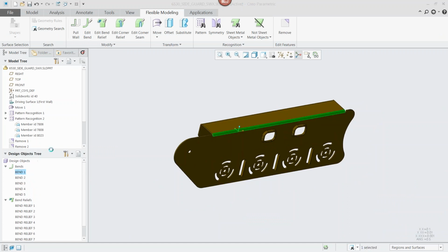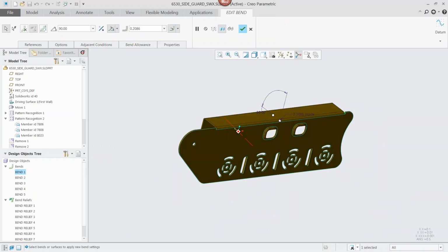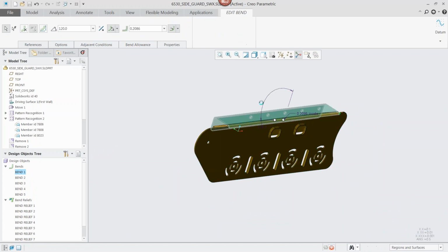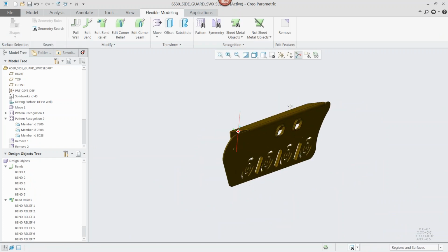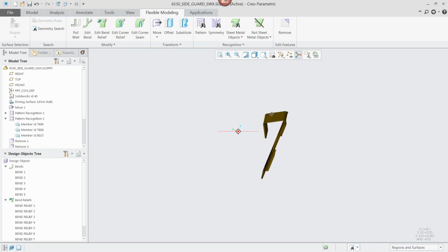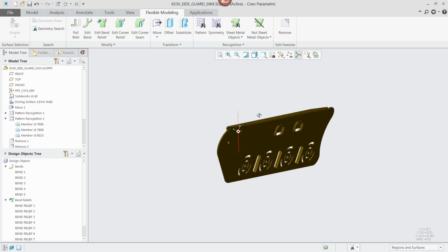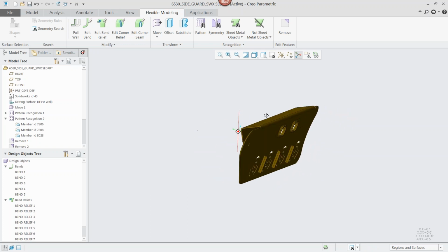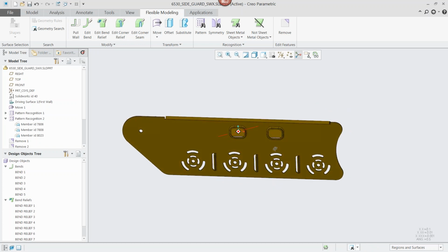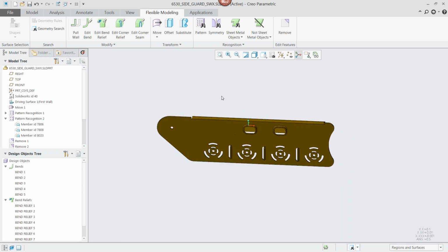Lastly, those bends, if I go through, modify that, maybe instead of a 90-degree bend, we want 120. You can just accept that off, and it's going to change this model. So a lot of different power with Creo on how we can not only bring in imports without having to worry about import failures, being able to natively open, we can also go through and modify those with flexible modeling. So giving us a lot of different things we can do with our toolbox there.